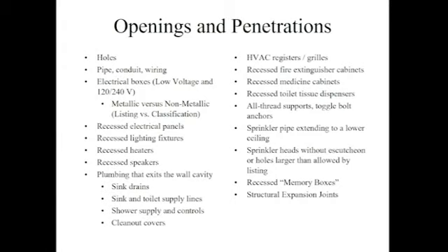But all the exterior walls, most of them in a one-story wood building, are bearing, and bathrooms end up on the exterior wall all the time, or on the corridor wall. The bathrooms in a nursing home end up on the corridor wall, and so you end up with a lot of penetrations that get forgotten and end up having to be fire stopped as an afterthought, which is not the appropriate way.